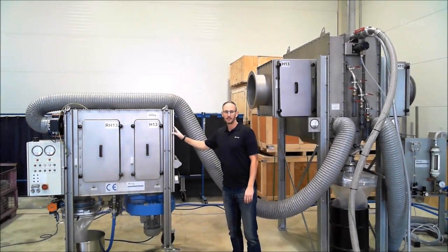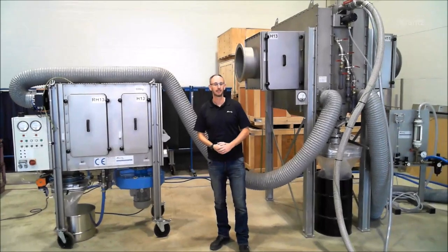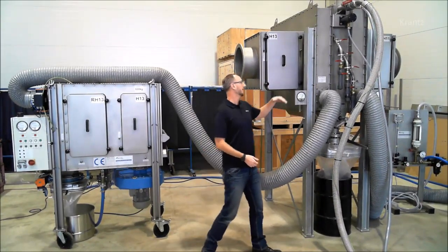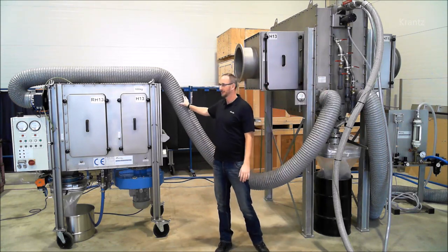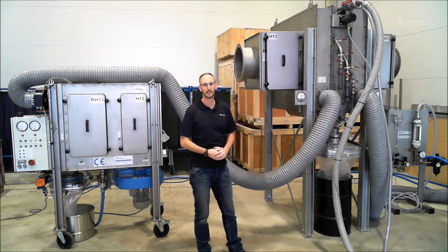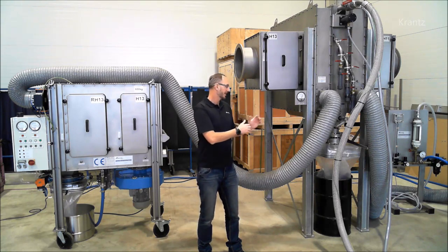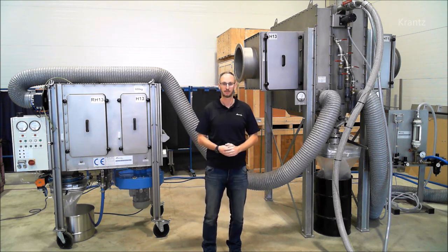And with this combination of air inlet and the re-cleanable filter housing, we are able to maintain a loop, so that during the filling of the carbon, the dust will be collected by the re-cleanable HEPA filter and fresh air is going into the housing to avoid negative pressure inside the housing. And as a next step, we will show you now the filling itself. So we will set up the equipment in the right position, and then you will see how we will shoot the carbon into the housing.